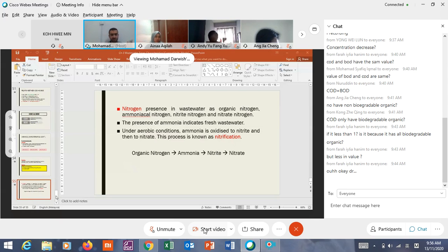The physical characteristics of wastewater: we talk about temperature, pH, odor, and the most important, the suspended solids. We talk about total solids, dissolved and suspended, and we also have the volatile and non-volatile solids. And how to measure each of them.